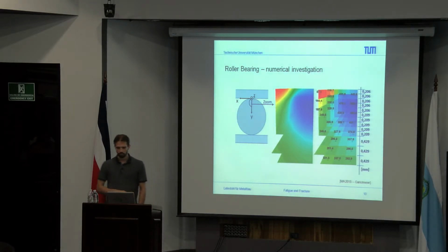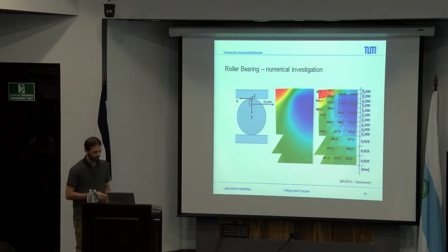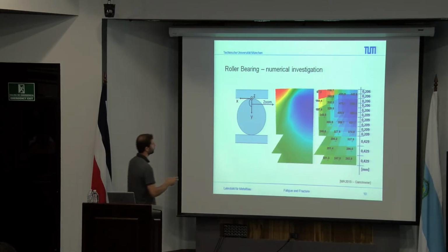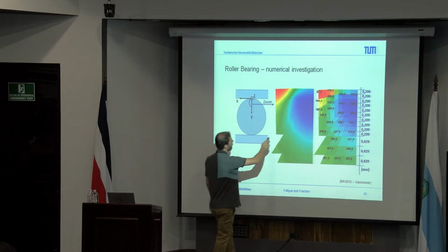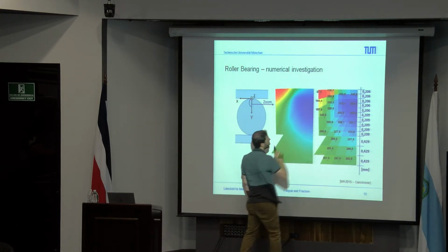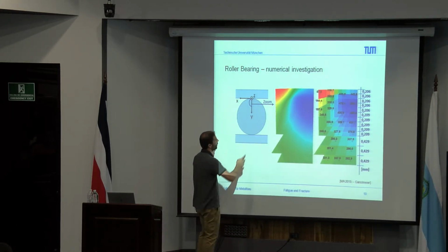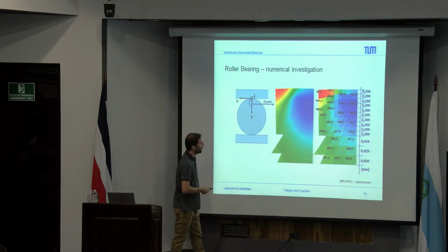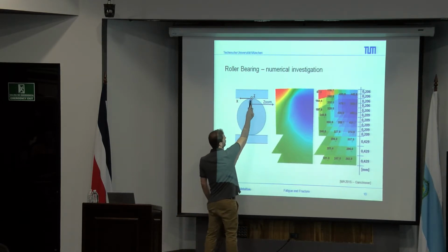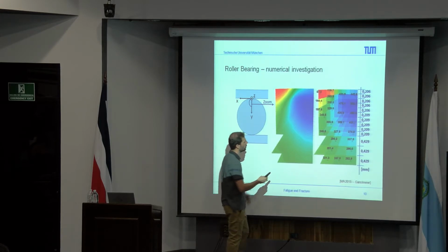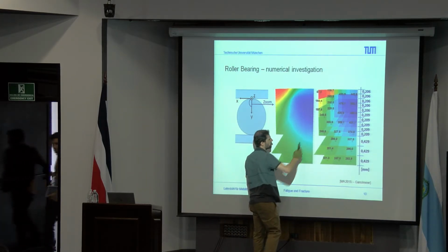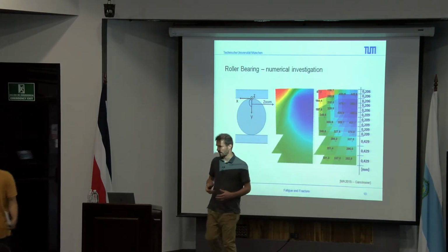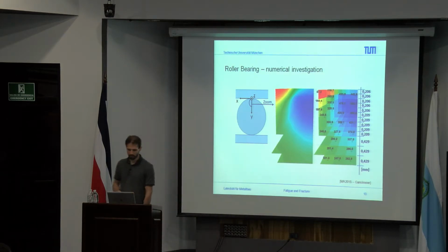And how does it look like if we now go into our stress state? So next to our crack tip, of course, we have here at this part the high pressure. Next to, we get into some tension zone, and here, as you see here in the half moon, this is how the stress is acting on the roller bearing itself.